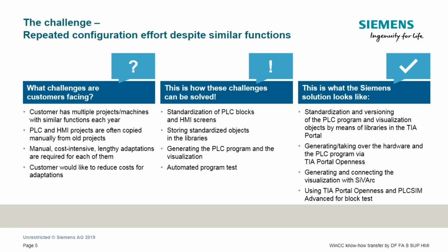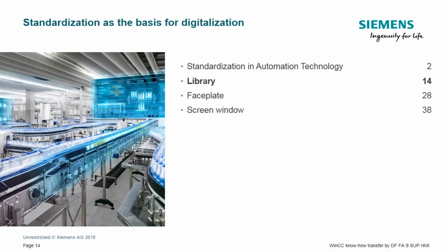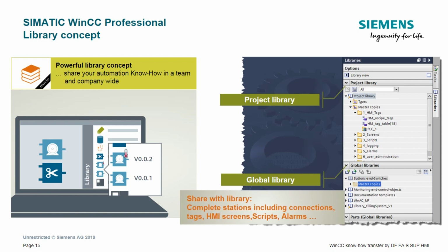Okay, so this is the basic stuff. To go into more detail regarding library management, how does it look in TIA Portal? You see here on the left side, when developing our standard for PLC blocks, we can also use versioning, so library management includes versioning. We also have a very nice application example for how to use libraries in TIA Portal, and I also included the links in another slide, so we will see that later on. It includes a very, very detailed documentation regarding how to use library management.